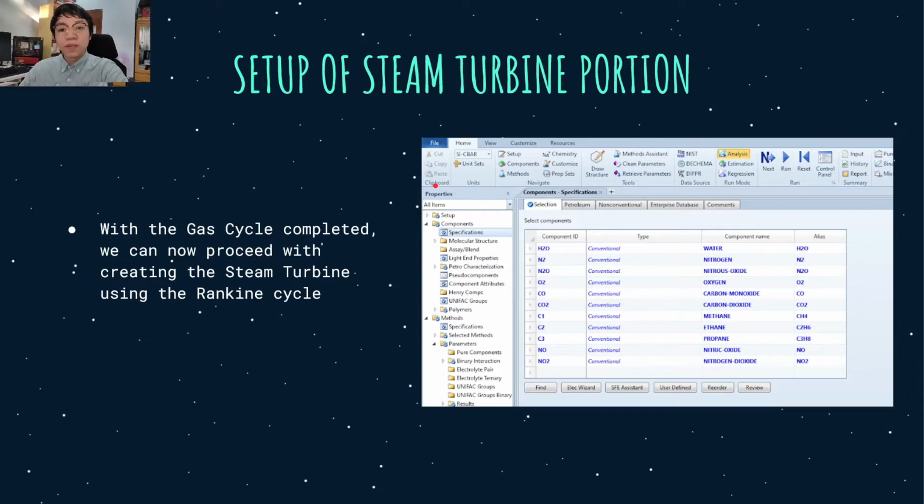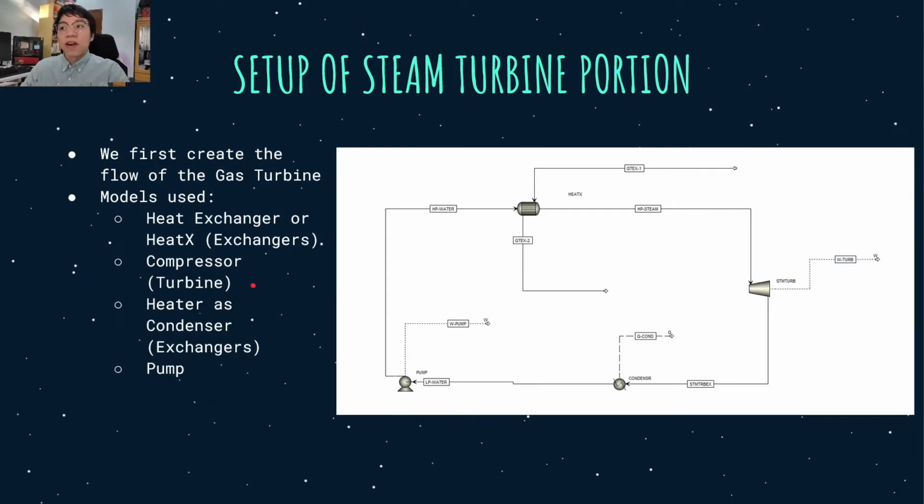Now to set up the steam turbine portion, we've already completed the compositions and even some of the needed chemicals for our simulation. So we're just going to piggyback off of our gas turbine simulation. So to set up for our steam turbine portion, we're going to use the following models. A heat exchanger, which is a MultiHeatX found on the model palette on Aspen Plus. We're going to require another compressor, in this case our turbine, a heater from the exchangers portion of the model palette, which will act as our condenser, and finally a pump.